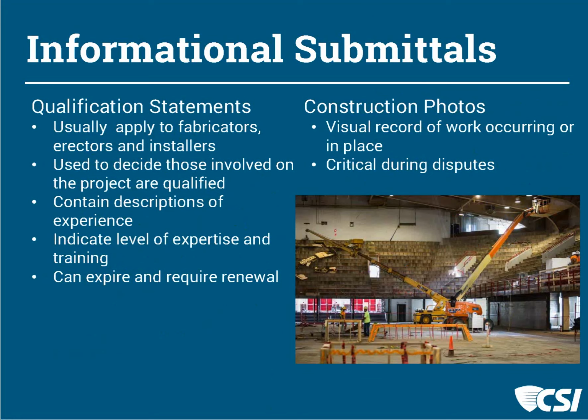All right, we have a few more questions that have kind of popped in here. One from Bobby asking, where in the CDs does it state informational submittal specifically? Is it in specs or somewhere else? Yes, I would include it in the specifications. Actually, if you go to the practice guide in Chapter 5 and take a look at that, I would absolutely break down my general conditions into supplementary general conditions and include these descriptions of the submittals that we are going to take action on and the submittals that we want to see as informational.